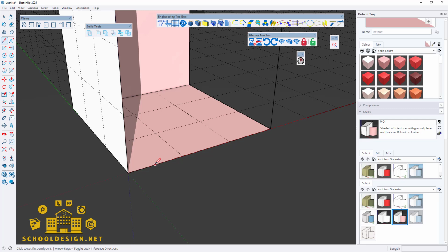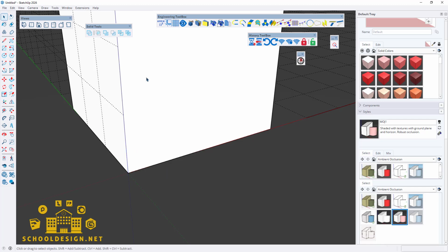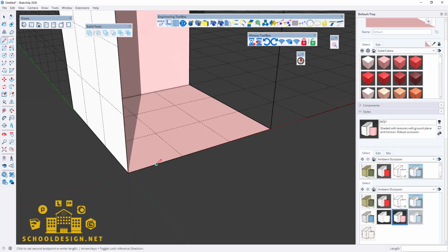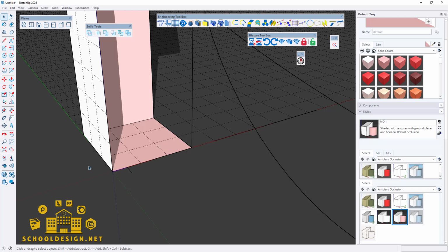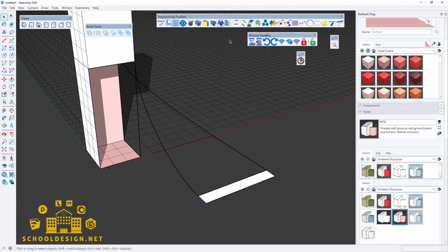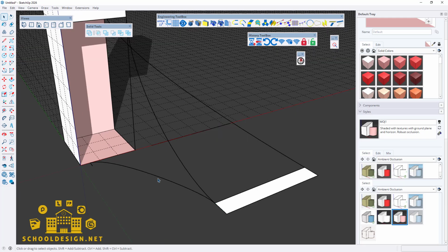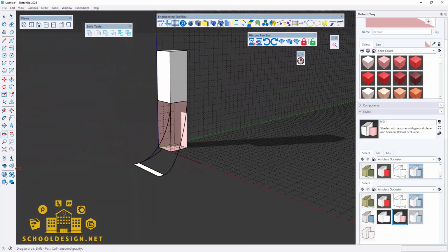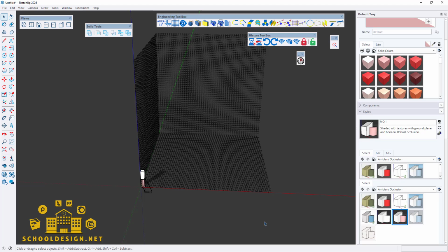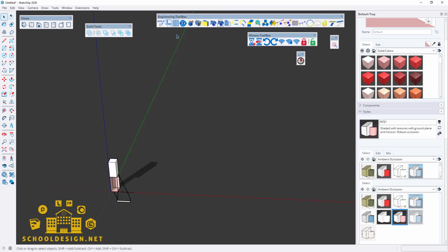Now we need to create one more line, but for this I need to create the supportive lines, and maybe in half. So we'll add the midpoint, and I will use those two lines for creating the smooth G1 bridge lines. Also a value of 0.5 for the transition should be okay. Okay, maybe the grid is too big, so I will just decrease the size, and now it will be perfect.